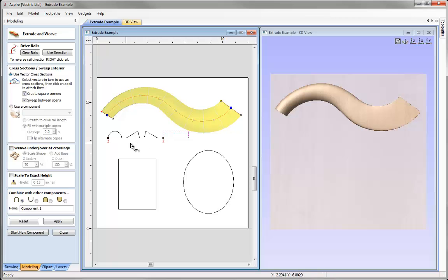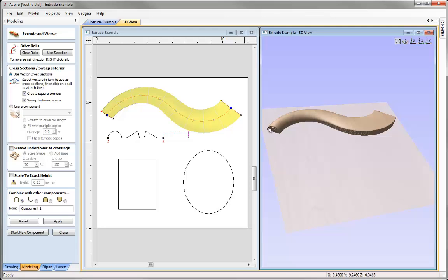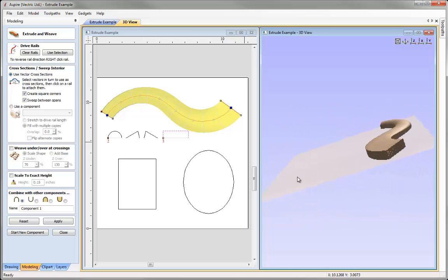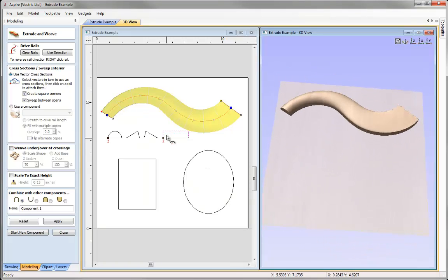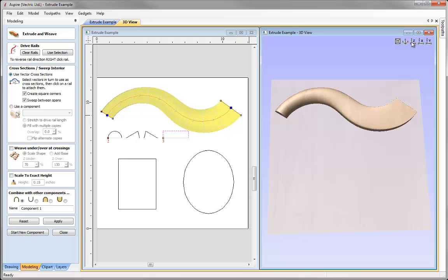into account this new shape on the end here. We can see how that looks. So we can see we're starting off with that rounded shape on one end here, and then it's going to come round, and then it's going to transform into this rectangular cross section that we have on the end there. And we know that our rectangular shape is a lot wider than our curve shape, and so the software has then taken into account this shape, and so my overall shape gets wider as it travels from one cross section to the other.